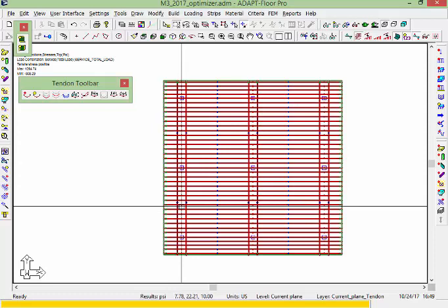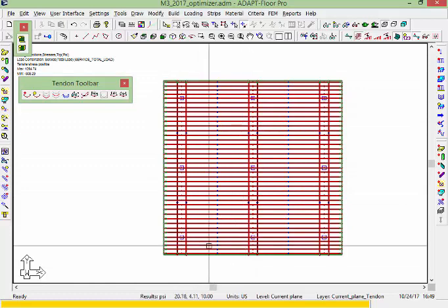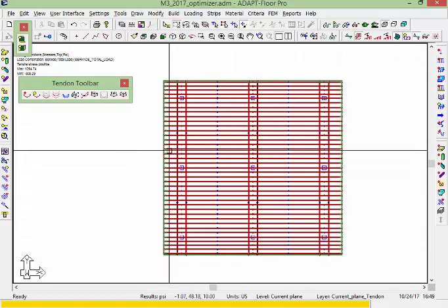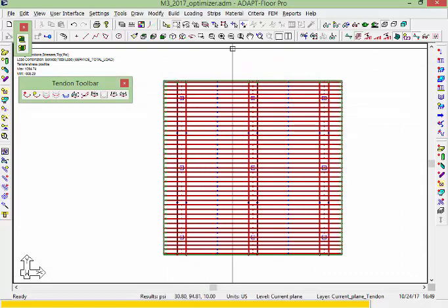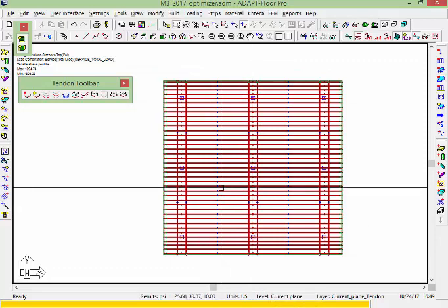Remember, we left off in the last design loop as 1115 kips for this middle bay, and we're now going to optimize the outer bays first because they're bound by the edge of the slab. When we optimize those, there's nowhere for that force to shed at the top and the bottom side of the slab. So this is a different approach to designing the same direction, and this is more economical and more efficient of a design than the previous design.